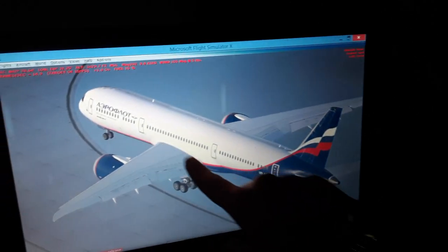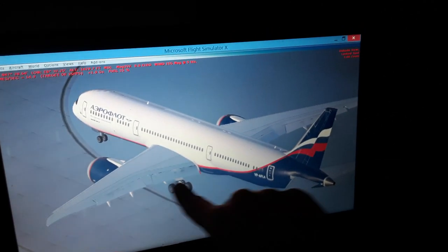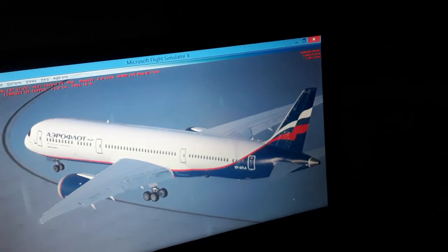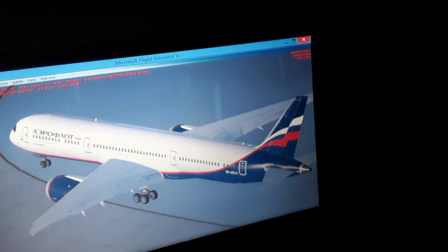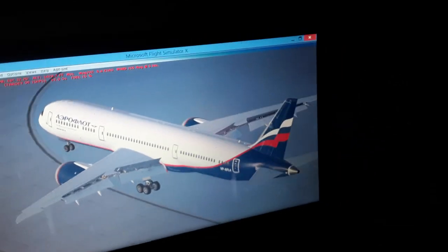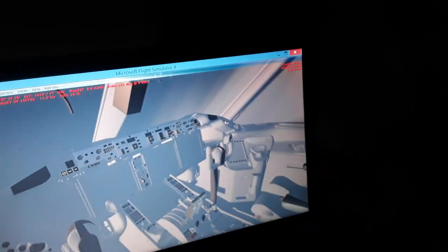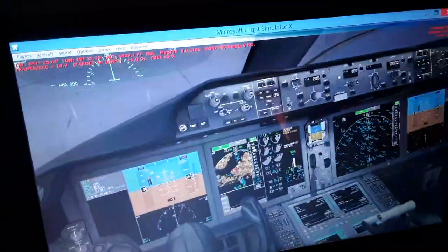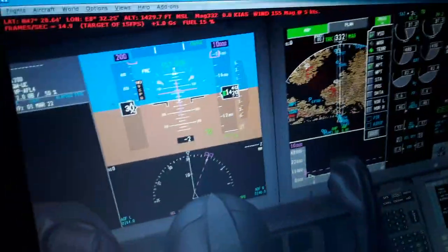The airflow becomes detached from the top surface of the wings for a given angle of attack and airspeed that changes. So the airflow becomes detached from the top surface of the wings, and the aircraft is going to start falling. So we need to avoid the stall speed. In the air we pull the side stick or yoke down and advance the thrust levers to increase the airspeed and decrease the pitch attitude of the aircraft.